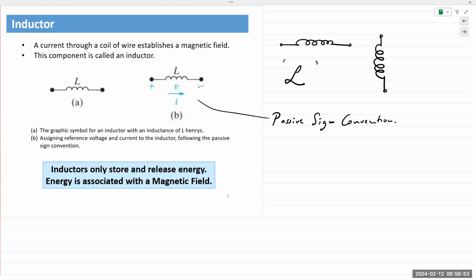Okay. One thing about inductance, if the current is constant, then the voltage across the inductor is zero. And we'll again look at mathematical equations where we can describe this quantitatively. But qualitatively, when current changes through an inductor, the magnetic field changes, and hence the inductance level is measured with the rate of change of current.